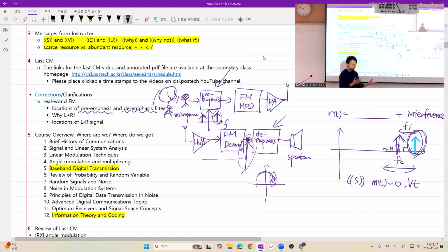However, what I explained during the class meeting, the pre-emphasis and de-emphasis filter has to work in the passband. And also, it must be carefully tuned. Otherwise, we have some nonlinear distortion. However, here, since the pre-emphasis filter and the de-emphasis filter directly work on the baseband, for example, voice signal, even though there is some distortion, as far as interference is a lot suppressed, that is very tolerable.